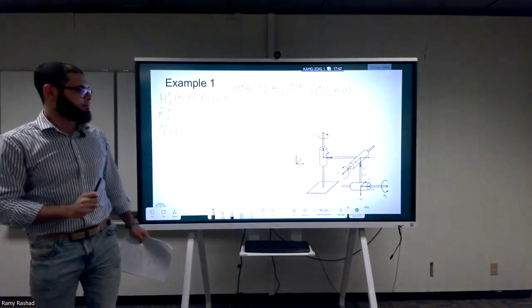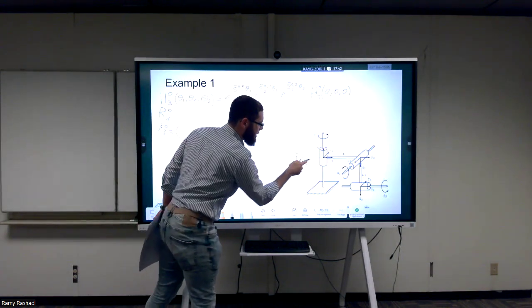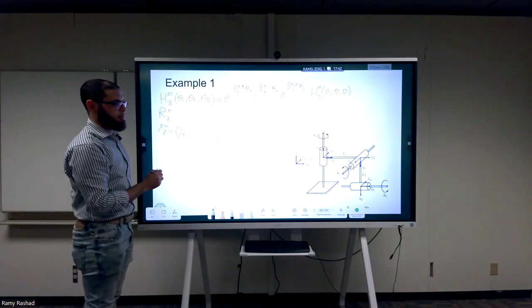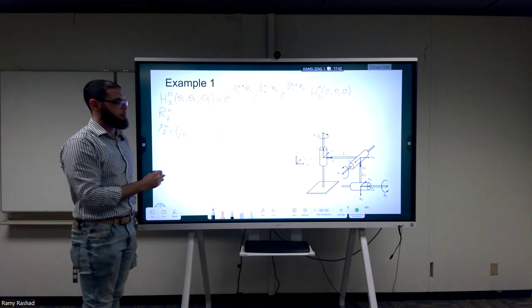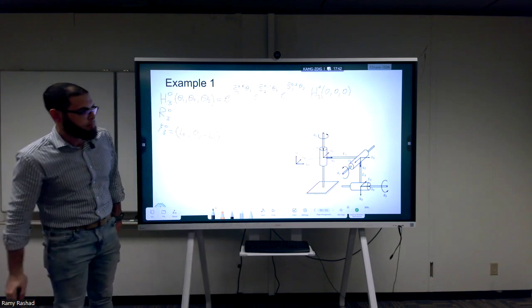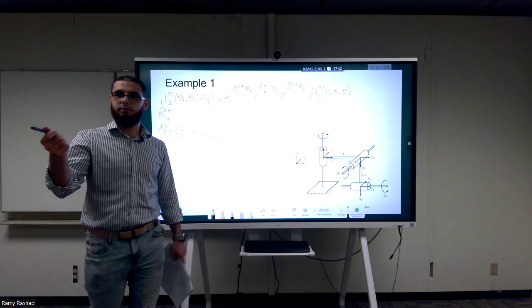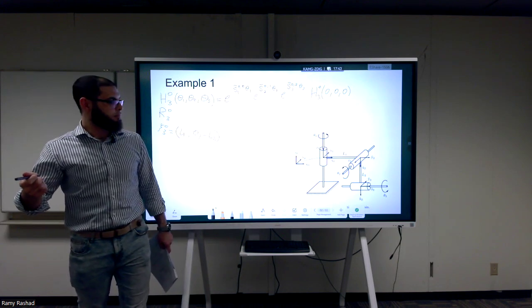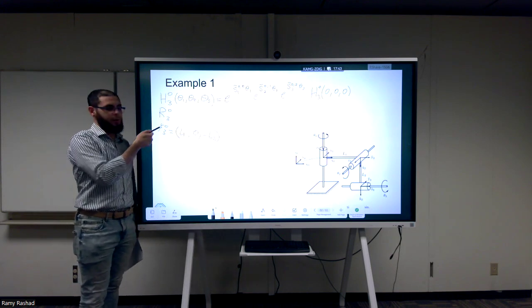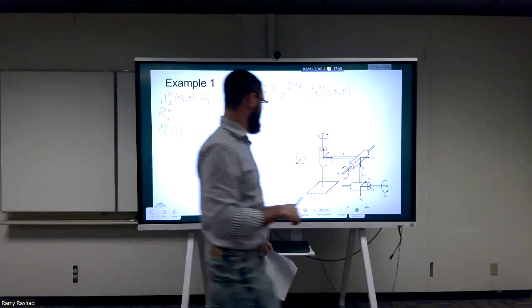So give me some numbers. The first number I should put here is how much should I move in this direction? So L1 and 0 and minus L2. Everyone agrees? The origin of the third frame expressed in the 0 frame. That's it. Y minus L2 according to the axis of the 0 frame.